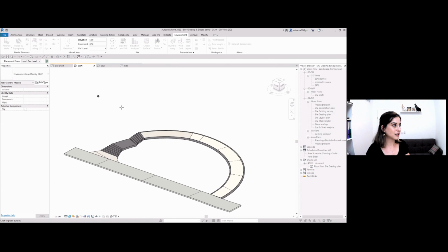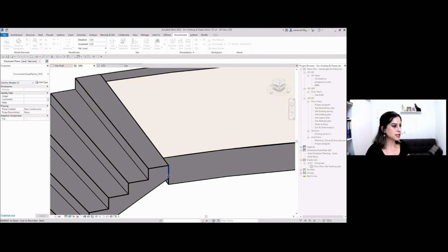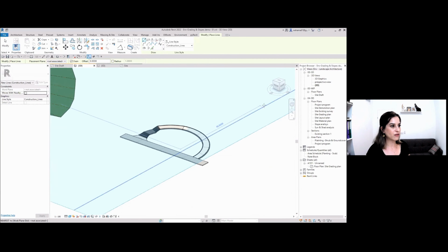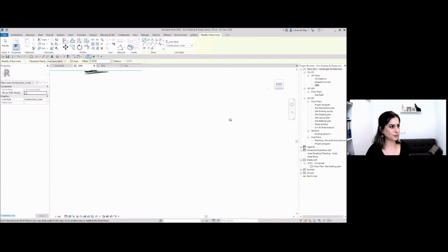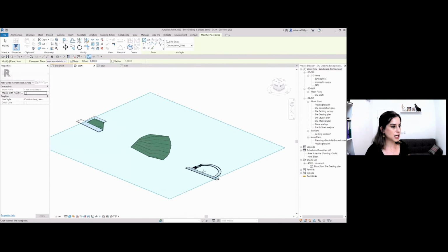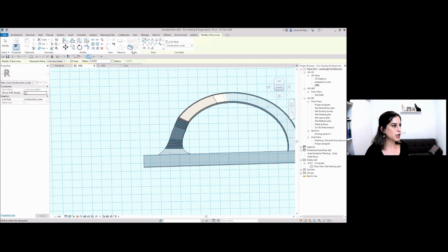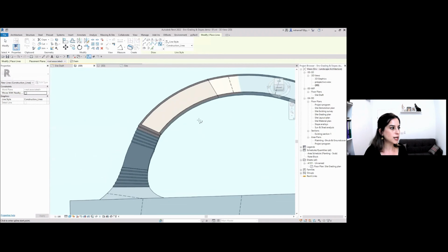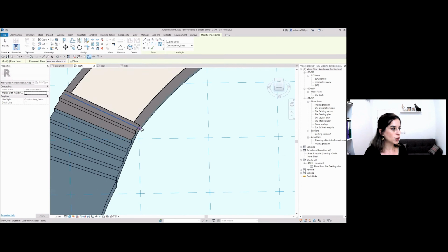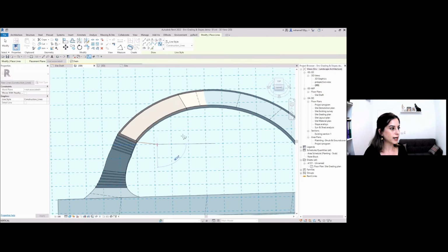So once I click on this feature, you can see I got this dot over here. And what I'm going to do, I'm actually going to snap to the edges of the stairs over here. And once I did that, Environment creates a reference plane. You can see it on the side. It's flat and it snaps to the same elevation that I just touched. Now, I can just go here and you can see that all the sketch tools are open, native Revit sketch tools. And let's select this line. So once I draw this model line, it will automatically be located in the correct elevation that I want.